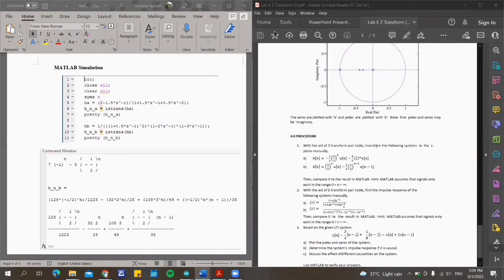For the MATLAB part, the inverse Z transform of a signal is calculated using the MATLAB function iztrans on the system H. The inverse Z transform for an IIR system may be determined in MATLAB by declaring the Z variable, declaring the system function, and performing the inverse Z transform on the Z-plane system H. Besides, the Z transform and the impulse response graph were displayed in the MATLAB results.